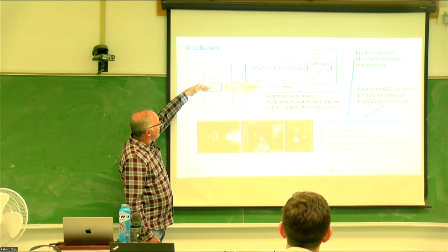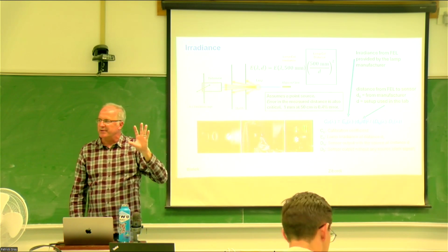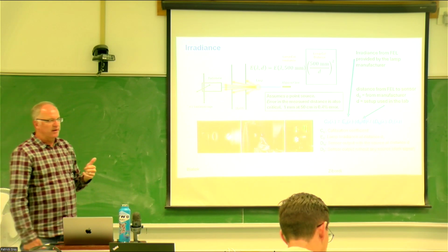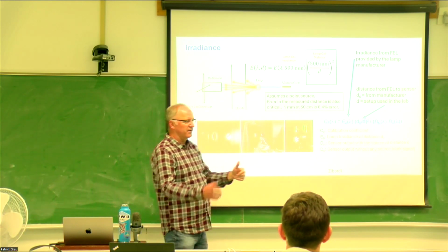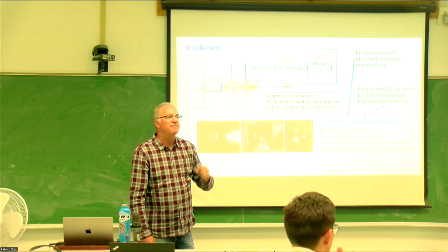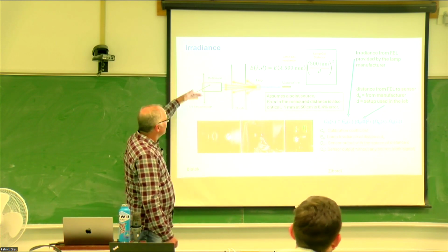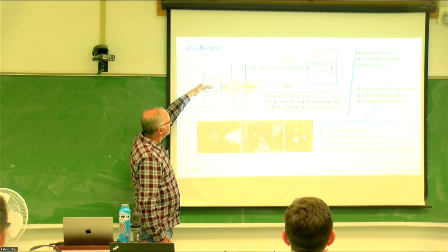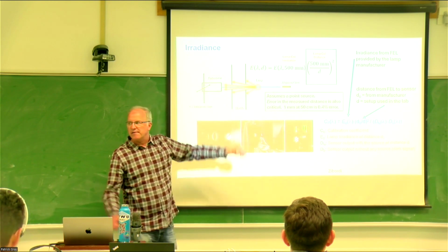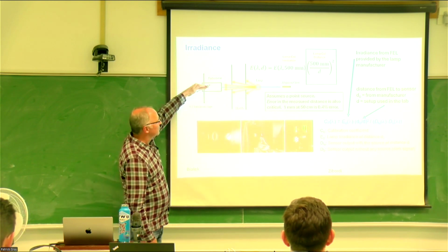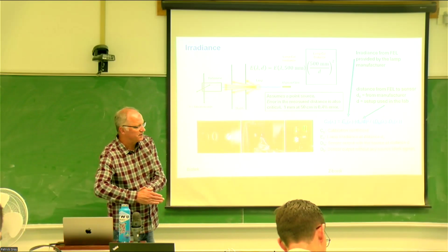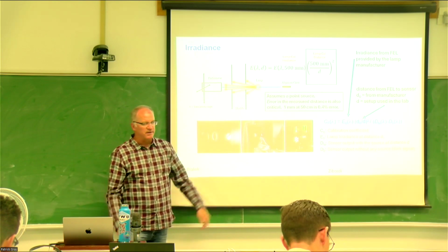So if I add, this is again, what type of a radiant sensor? What's the key characteristic of an irradiance sensor to recognize it? If you had a radiance and an irradiance sensor in your hand, how would they look different? Cosine collector. So what happens if I rotate the instrument this way? What am I measuring? Cosine response? Correct. So that's why this is here. Because all I have to do now is start rotating that at different stages, and now I'm measuring the cosine response of the instrument.